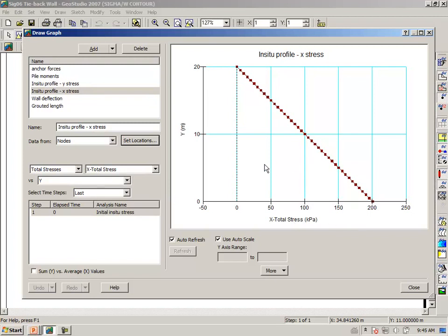In a few moments here, we will apply a boundary condition to the edge of the excavation, which represents the removal of this stress. And in order to do that, it is a special type of boundary condition, which we will see in just a few moments. But before we go there, we notice that the rate of increase here, we have a total of 200 divided by 20 gives us 10 kilonewtons per meter.